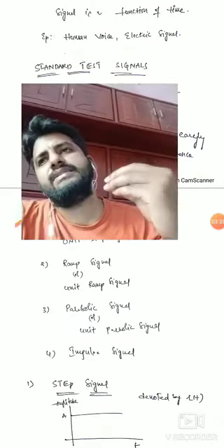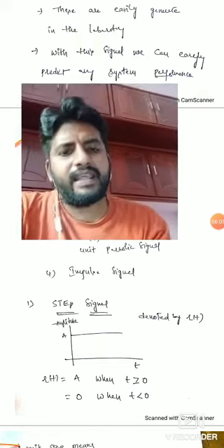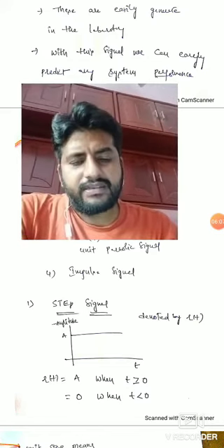So that we can call it a parallax error also. After that, environmental error, right? Due to the humidity, temperature, electromagnetic fields across the instrument, static fields, electrostatic fields. These are the things that will definitely create an error. So these types of errors we can call an environmental error.